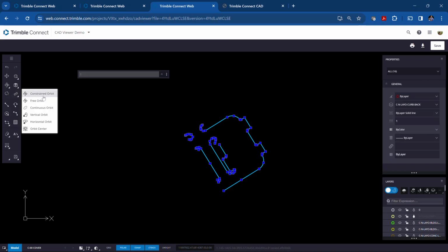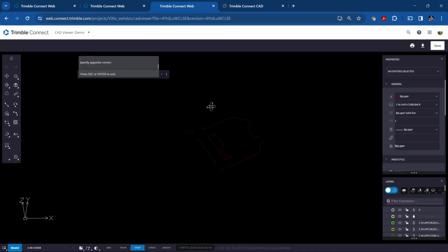So now let's take a look at what we got. If we go into orbit, and I rotate it up, looks like they're all zeros, right? So they're all zeroed out. So now I can just go back to top, and we can do the PEDIT again. Oops, so let's get that. So PEDIT. We'll do multiple. We'll just pick all the lines. Round 16. We want to convert them, yes. And then we want to join them.